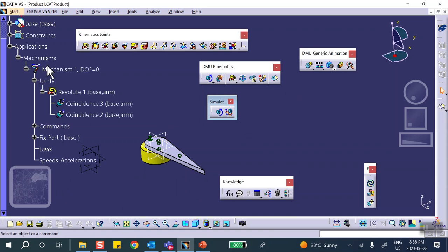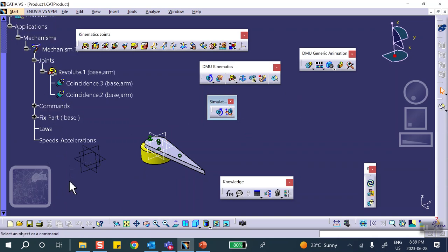Now, in order to have a record of all this, we're going to use the simulation toolbar. This is a very important toolbar. We already used the magic wand, and we already used the simulation with command. This is the other important toolbar. The very first one says simulation. Notice that before I do that, I made that angle-driven joint, and that is right here.